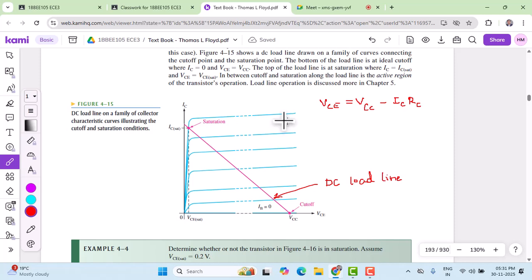Okay. From this we can estimate the collector current. IC is equal to beta DC times IB. So beta DC is 100, IB is 195 microampere. That gives us collector current as 19.5 milliampere. The current that is flowing here is IC, which is equal to 19.5 milliampere.